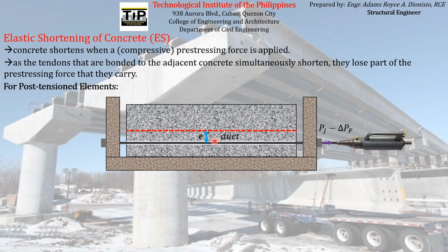That friction force opposes the tensile force applied by the hydraulic jack, therefore reducing the force experienced by the pre-stressing reinforcement as the jack applies a jacking force at this particular stage of the pre-stressing operation.